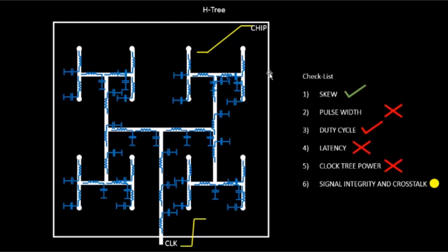So in this case, why are we not good on latency? The reason is that the transition at the input and the transition at the output are way off. The transition should be at least very close to what we send at the input. The number of repeaters that we can add in this circuit depends upon the transition. We'll be talking about repeaters and buffering in later sections of this slide. So latency is a cross for us.